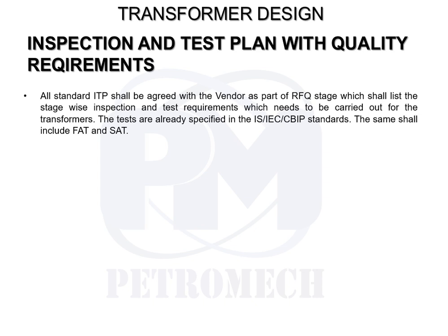You have to specifically mention that in your offer stage document itself, that this is a particular specific type test that we want to witness at a specified testing lab.